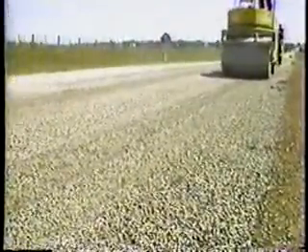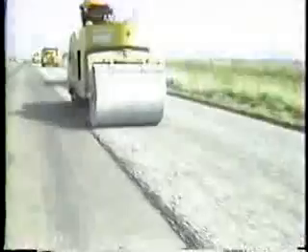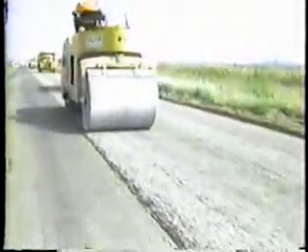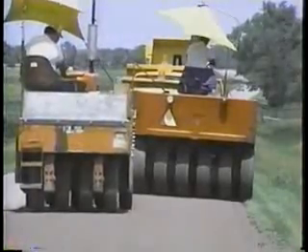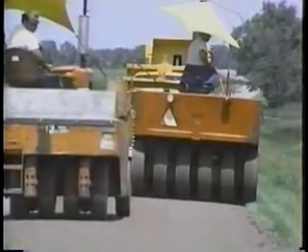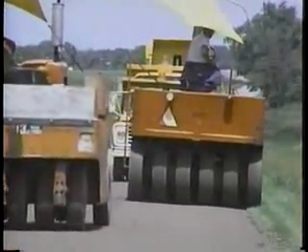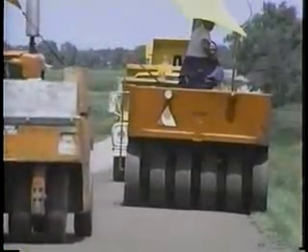Steel-wheeled rollers may be used to roll chip seals too. However, the drums sometimes crush the aggregate and bridge over low areas of the surface, so generally they're not recommended. As for the number of rollers, two or more are ideal. Your agency, however, may be limited on equipment, so the actual number will vary.